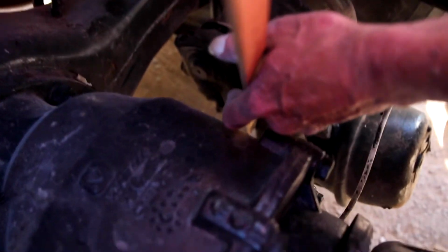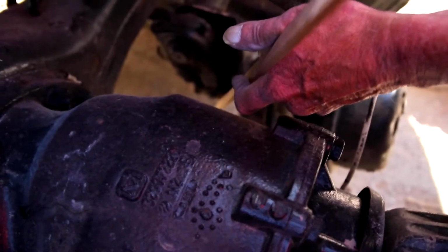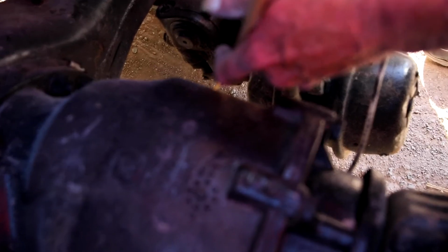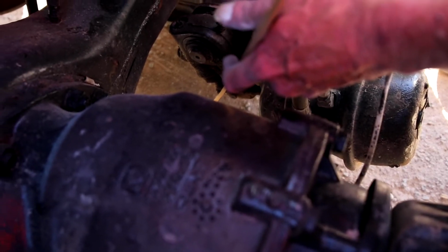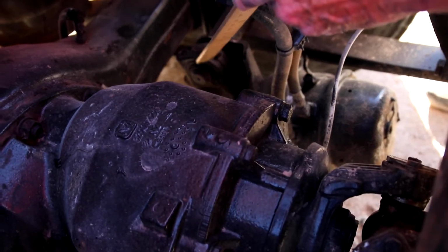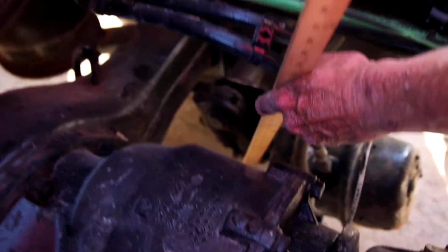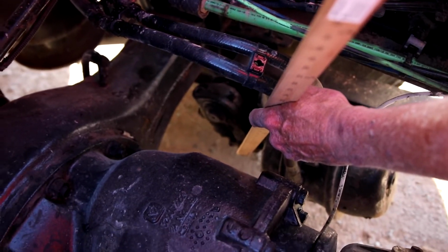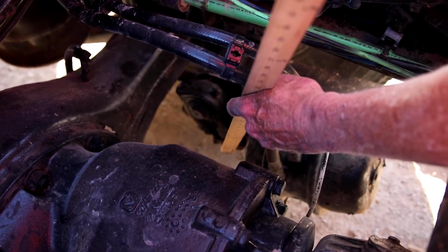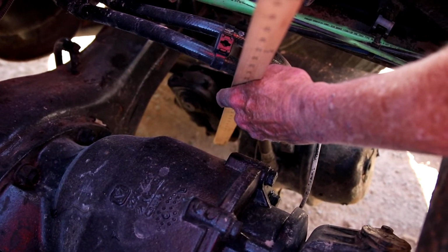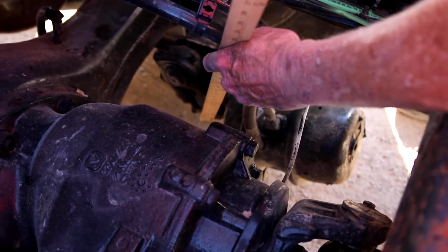Then you have another push rod way down here on the bottom side of this with clevis pins and cotter keys mounted to your slack adjuster. It is not missing, damaged, or broken. And again, when the brakes are released, you should not be able to pull more than 1 inch on the slack adjuster. Moving to the inside to your brakes.